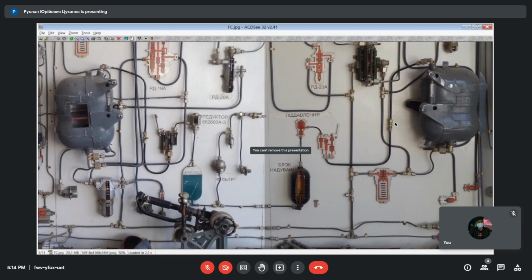These sources are interconnected, and of course here there is a check valve, and here there is a check valve, to prevent air release via an inoperative engine and ground connection in flight. Next, air is always supplied to the air filter. This device is the air filter. So air supplied to the hydraulic system from outboard must be filtered beforehand to prevent mechanical impurities getting into the hydraulic system. Let me a little bit. And next, behind the filter, there is a T connection.